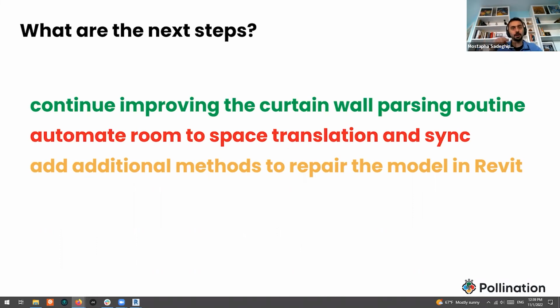Or you can draw your HVAC zones if you want to merge these rooms together and you think that's a lot of details. You can draw a few areas in your level and say, I want this to be exported as 1, 2, 3 areas. And then we take those instead of exporting every single interior wall that you have.